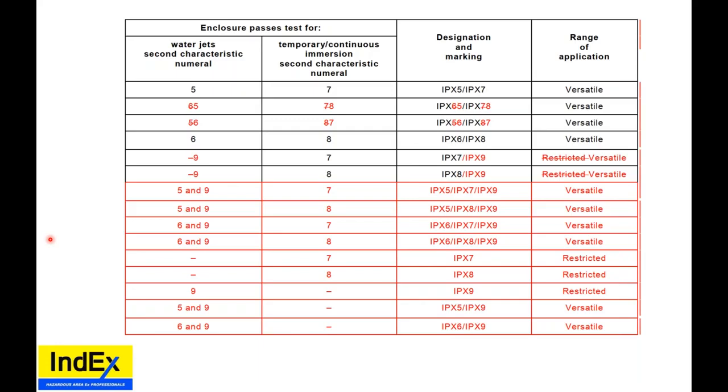Is IP applicable for any enclosures such as valve actuators? For a mechanical device, if there are no electrical connections, a manufacturer can still ask for IP testing. Now, it's supposed to be for electrical components inside, but some people apply this standard to mechanical devices. Now, when we come into 80079, the mechanical standards, these IP ratings can be beneficial. So there's still confusion within the industry.